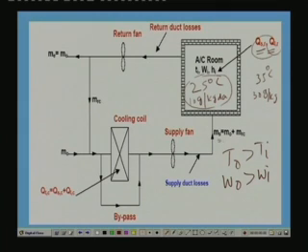In the air conditioning system, what we do is we supply, for this case for example, a supply air which is cold and dry. So, cold and dry air at the required mass flow rate is supplied to the building. This cold and dry air flows through the conditioned space, and as it flows through it, it picks up the sensible heat and the latent heat, and we assume that when it comes out of the conditioned space, its conditions will be almost the same as the conditioned space conditions.